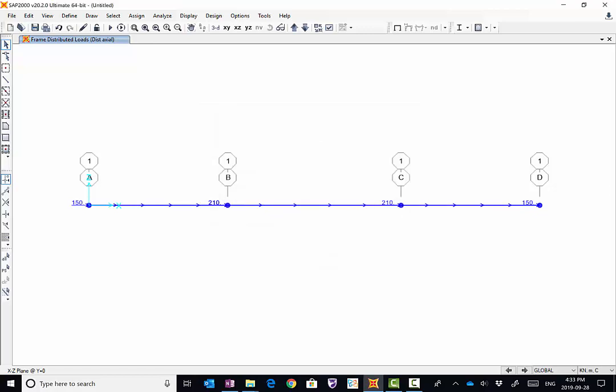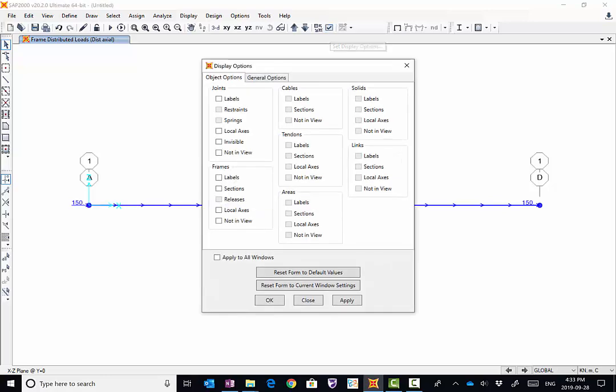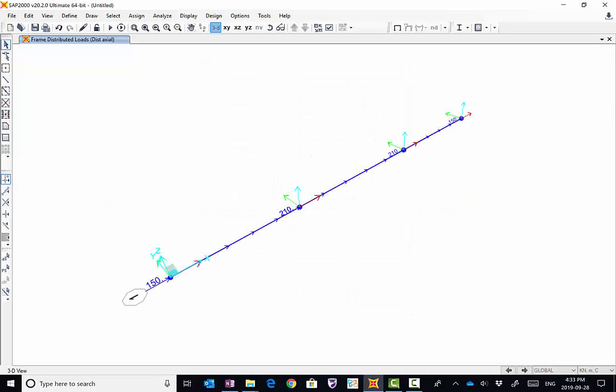The second part now: how to apply the boundary conditions. Again, don't forget the local axes for the joints. I'm going to highlight that again. In 3D, I want to prevent this node from translation along 1, which is the red. It's a one-dimensional problem. So in order to restrain this node, you have to restrain direction 1 locally, which is in the direction of X globally. So let's go back.